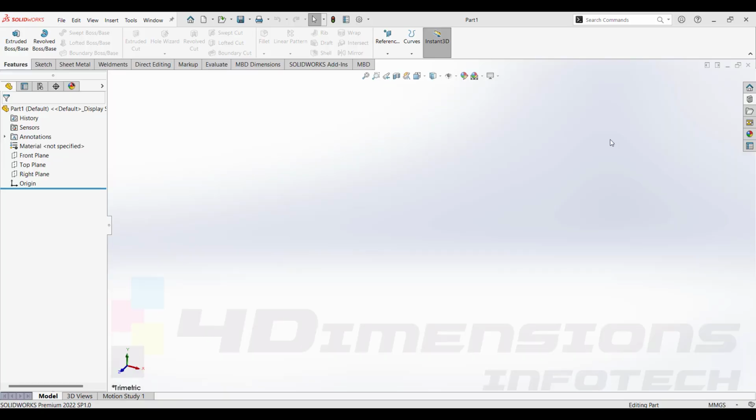Hello everyone. So today we'll start with session number 17. In previous sessions from 1 to 16 we have seen sketcher, part modeling and features, as well as assembly and types such as standard mates and advanced mates. So today we are going to start with mechanical mates, and in mechanical mates we are going to see gear mate and screw mate. So to start with the parts, we don't need to make parts of gear.